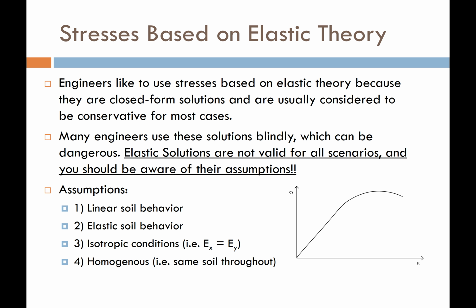Looking at stress-based approaches, stresses calculated using elastic theory, we like this approach for a few reasons. First of all, they tend to give us closed-form solutions. That means that we can get a very simple equation that you can just program into a spreadsheet or a MATLAB program. And these solutions tend to be conservative for most cases, meaning they're not going to underpredict the stresses usually, though in some cases they can.